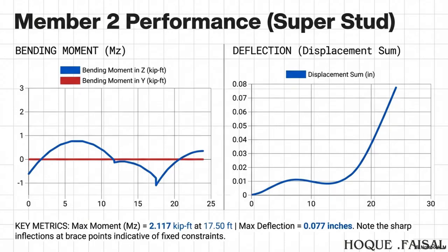Right. The connection itself is rigid. It fights back against the rotation. It transfers that push into a bending force along the whole length of the stick. That is a fixed connection. So fixed means rigid, welded, glued, locked in concrete, and released or pinned means hinged, bolted, free to pivot.